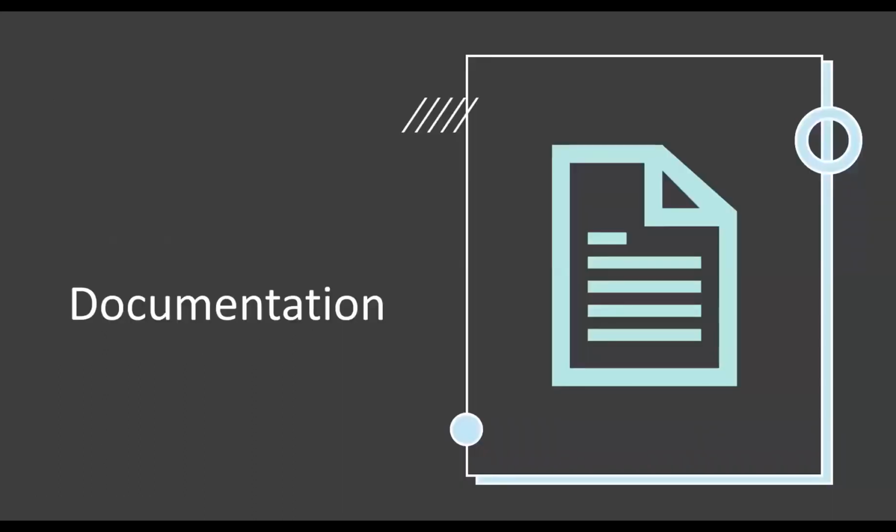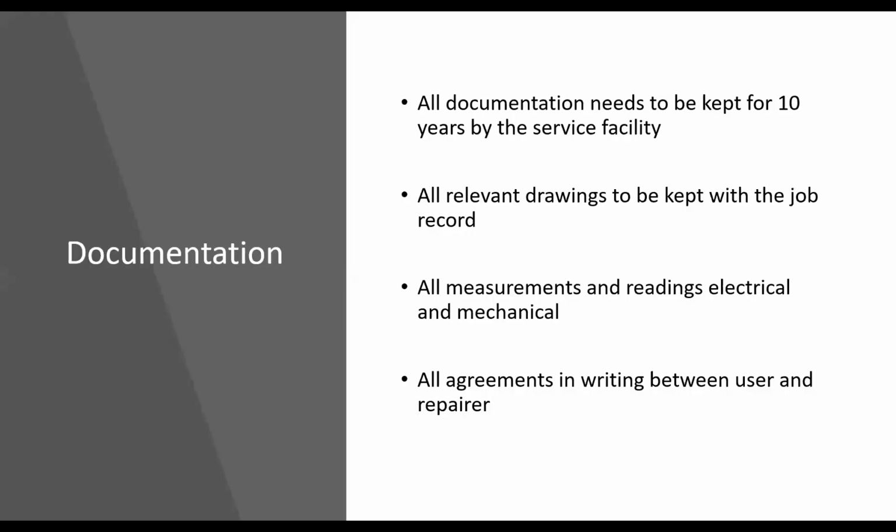Let's talk about documentation. What should be transferred between the user and the repairer and vice versa. The service facility should keep all documentation for 10 years. Again, this is a requirement of the repair standard. If there was an incident to occur and you repaired that equipment 7 years ago, you would be expected to be able to pull out the paperwork and show what had happened. And this is for the user as well as the repairer.